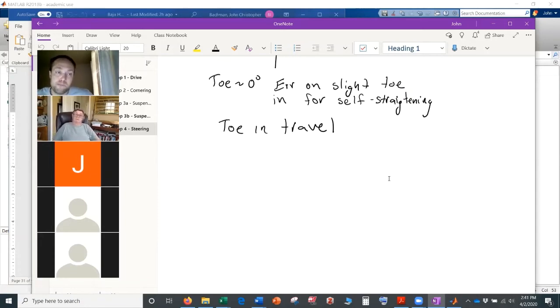Because I've seen teams on Formula do that because they say somehow it helps with the front grip, or something like that. Then also, as far as the caster in the back for Formula, I feel like it should lean more towards a shopping cart. That could possibly help keep your wheel straight in a sense. Instead of going positive, you could go negative.